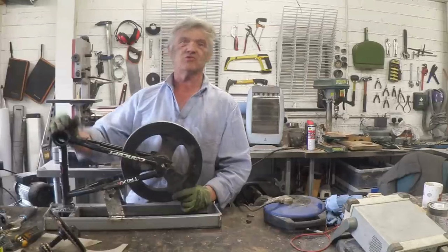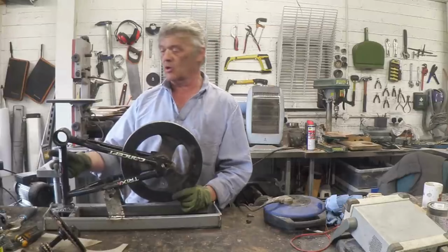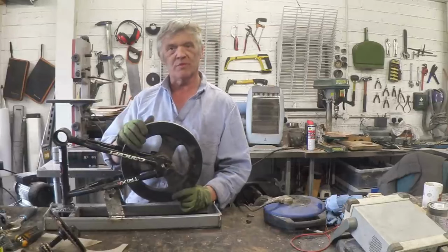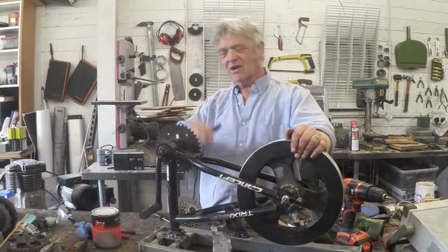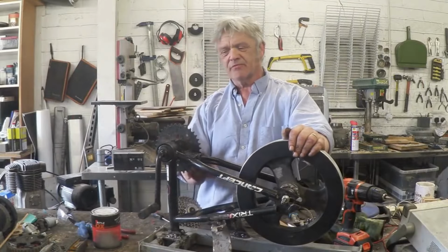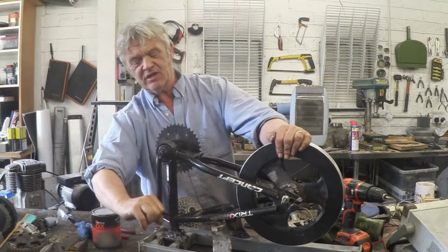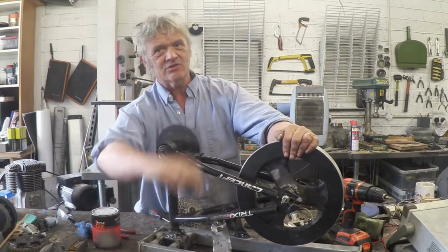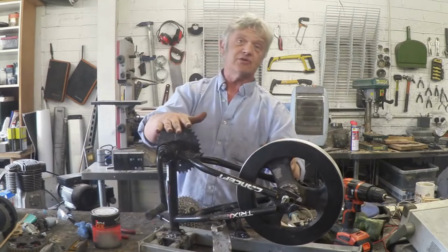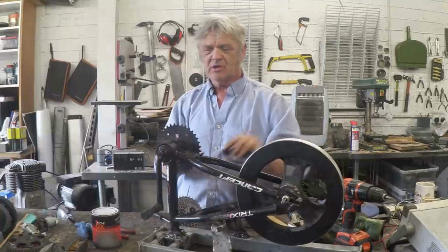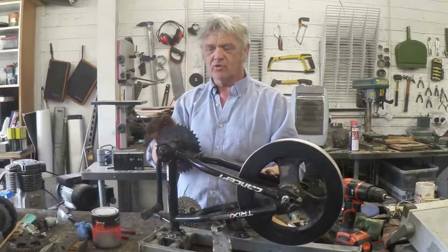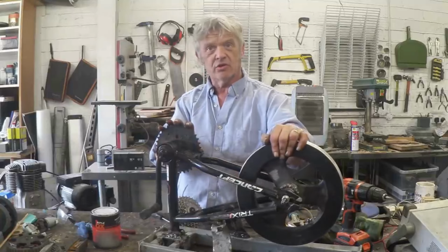And of course we've got this, which is square to that, so we can put a cog and crank on there, and it's going to spin that flywheel beautifully. There it is bolted back together. I chopped off the pedal on one side, chopped the pedal down to make a crank handle, so I can turn that, it'll turn this, connect the chain, and of course it's going to turn that. Now the gear ratio is 2 to 1, so every one turn of this, I get 2 turns of that.